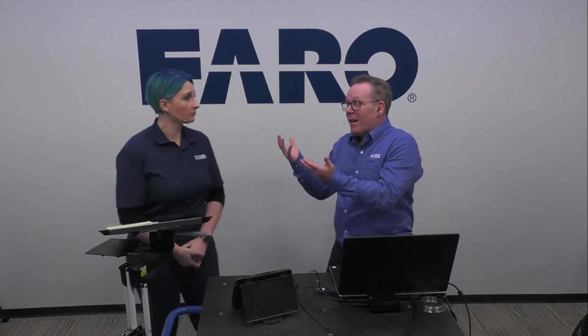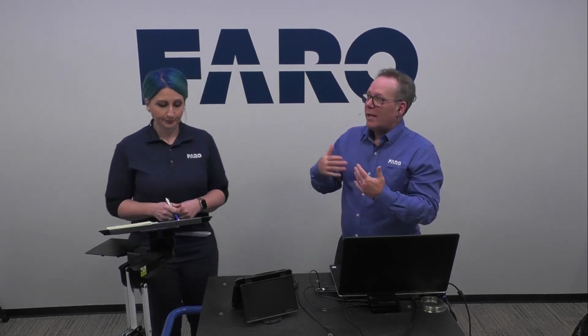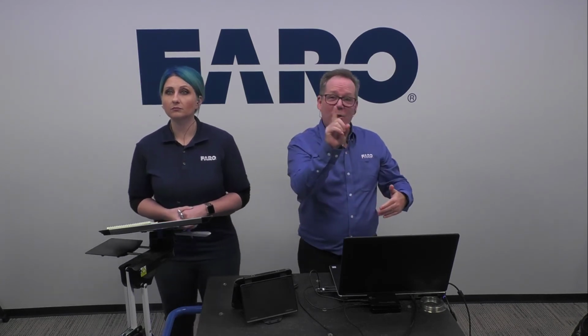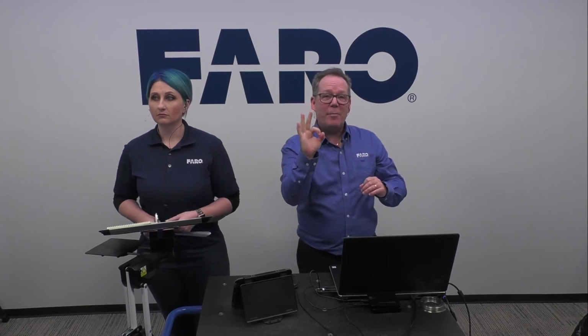Thanks for joining us. The answer is yes, if you apply the appropriate snap. There is a new, in my opinion improved, snapping system in the FARO Zone software. If you're using point cloud data, you just activate your point cloud snaps. All you've got to do is click on the point cloud. You'll see your snap circle appear to indicate that you're hovering over point cloud data. And yes, in that report, you'll get the z-values. Done.